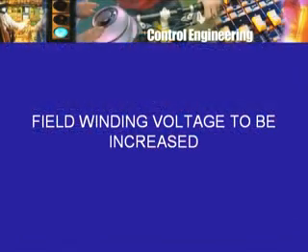So the field winding resistance is not going to be small. As a result, if you want to have 3 times the field current in the field winding, the voltage that is applied to the field winding may not be adequate. So now I have to have a field winding for which the supply voltage can be increased. There are of course limits to increasing the field current, as I mentioned earlier, because of saturation.